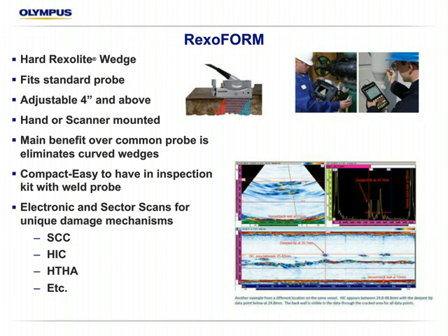diameters. It's also very compact. The probe used with it is a common phased array probe used for weld inspections and other surveys. So if you had a master kit that you like to go out with and you weren't expecting to do corrosion mapping, this would only add about 2 inches in your kit. You could just grab it and be able to do corrosion surveys on the spot, or even lamination checks or anything else you might want to do more at 0 degrees versus angle beam.